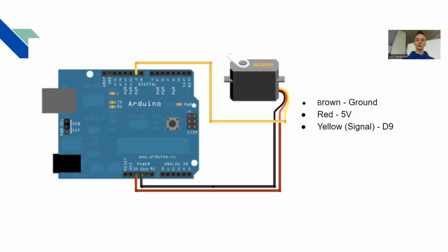So this is the way I recommend setting it up. I believe that's a PWM signal pin 9. Brown is ground, red is 5 volts, and yellow is signal. I believe the ones we have actually have an orange wire for the signal pin, and a red and a brown one for voltage and ground. Make sure that you actually give these things 5 volts.